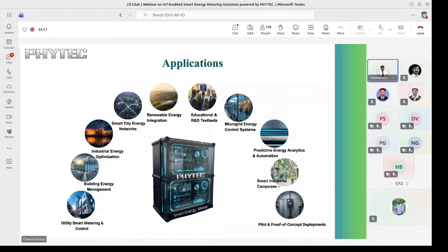This is basically one prototype of a smart energy meter, where we have an NXP Cortex M0+ SoC, the MKM35Z512 processor. If you see here, we have a display unit, a crystal oscillator, a GPRS module, and RS-232 communication. We have tamper detection: if some tampering happens, it will give an alert to the utility. We have an auto push button, which scrolls to the next reading, and an IR communication LED is also there.